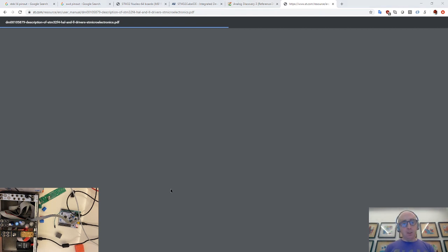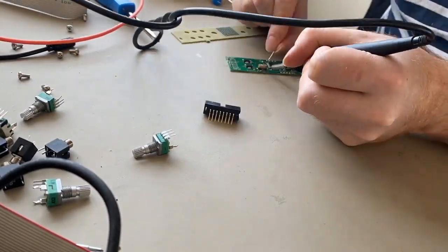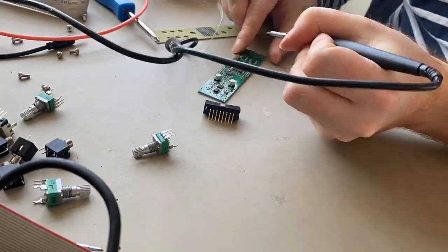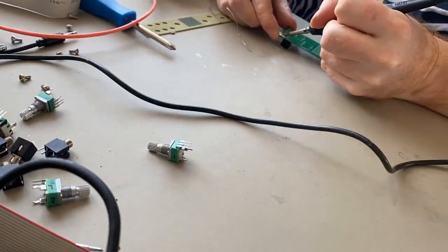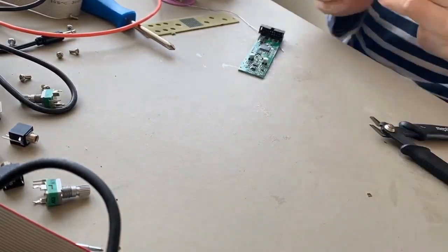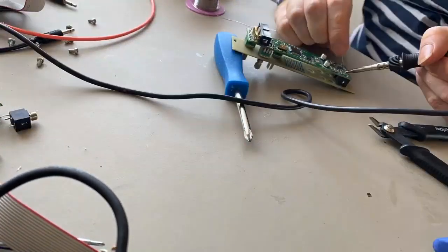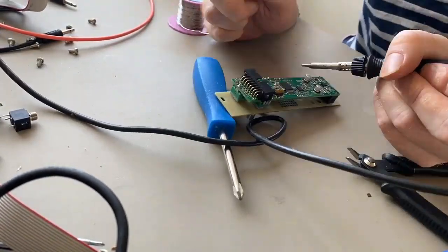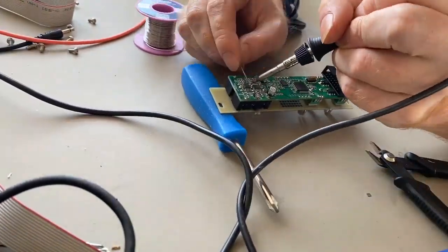But now we're actually going to start building. I've got a little video to play, which is me soldering a bare board. The first thing I put on is a 16-pin programming header, which I'm going to talk about in a moment. The SMD stuff was done in China by JLC for a ridiculously cheap amount of money. Look at the flux-stained table, horrifying. All I had to do was stick on the through-hole things. I didn't have a straight power header, so I put in a right-angle one. Luckily, it fitted.